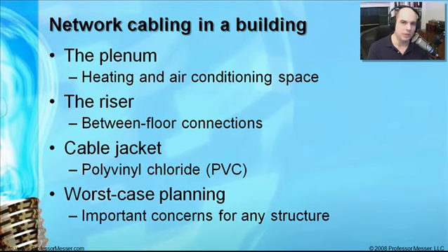It's one that is not going to take a fire on one end of the cable and burn all the way to the other side. This is why whenever we look at putting cable into a plenum, putting especially copper or fiber cable into these risers, that it is rated, and it's usually a little more expensive because it's rated this way, not to catch on fire. So even though we're paying a little bit more for that type of cabling, just keep in mind that now we are not going to have to be concerned about fire spreading that way.